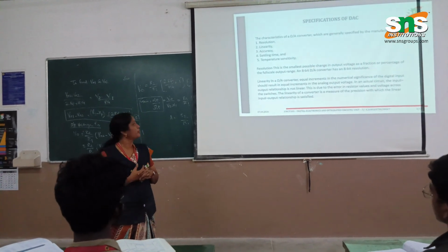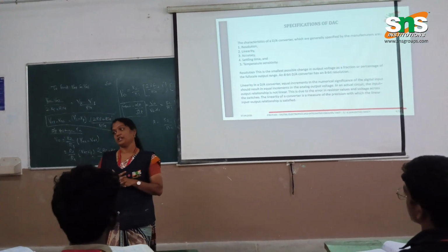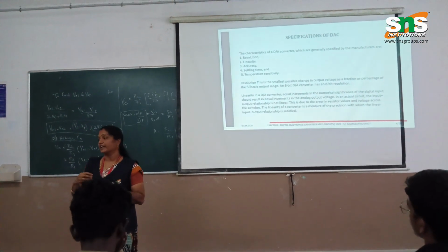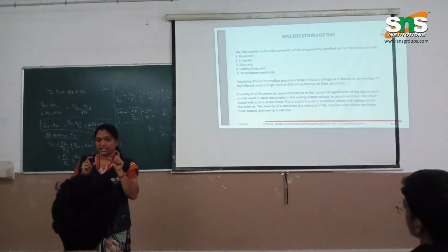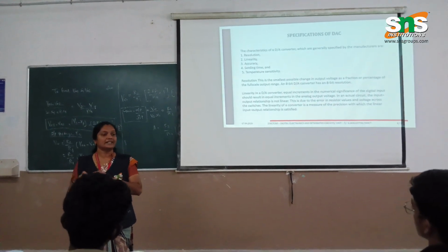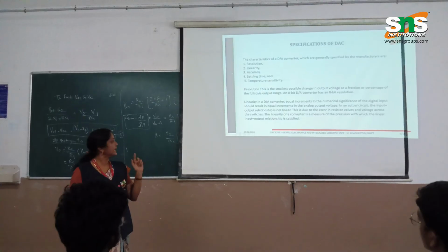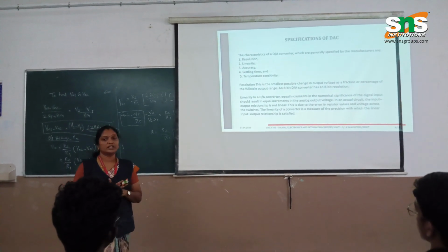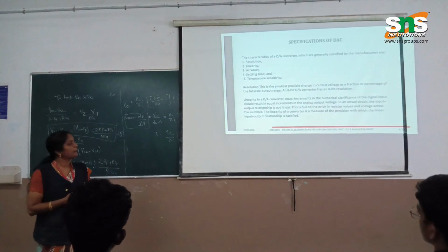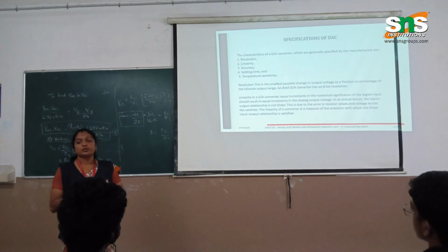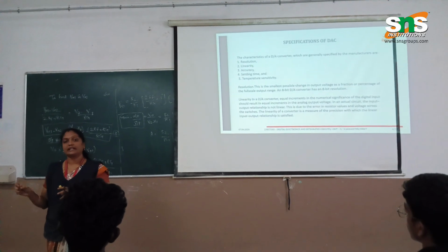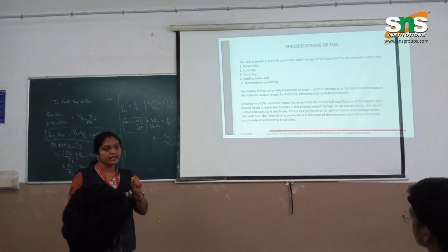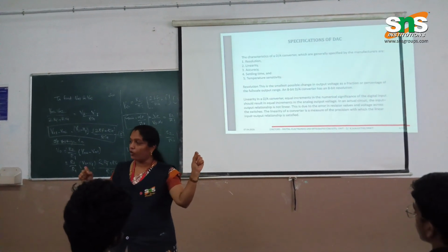Next, there are some specifications to define a DAC. There are 5 points, and the first one is resolution. Resolution is the smallest change in the input that should reflect in the output. And the next one is linearity. Linearity in a digital to analog converter means an equal increment in the digital input should result in an equal increment in the analog output. If we increase the input signal, it should reflect in the output also.